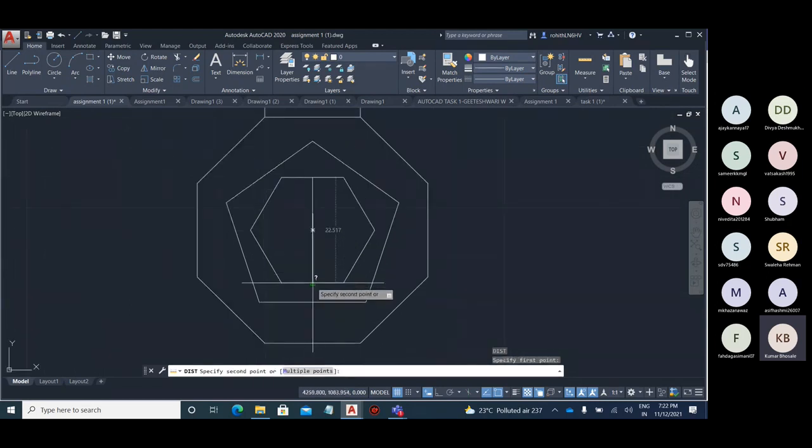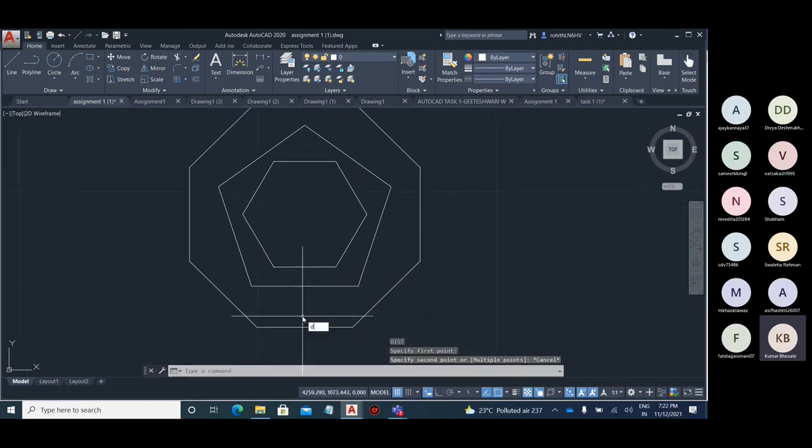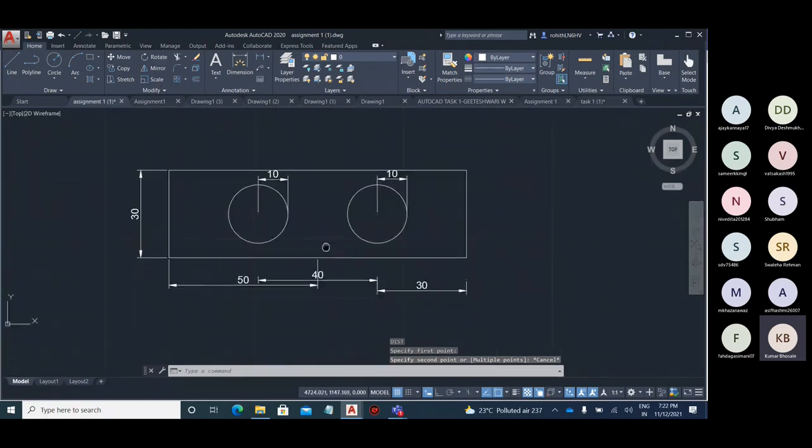Over here this is wrong. This is again created as an interior circle. That is not a circumference, so make sure of this. This is an inscribed circle. Polygon is created by having an inscribed circle. It should be circumscribed. So you can see the distance is 22.517 and the distance given is 26. So this is not created perfectly. This distance from here to here should be 6. It is given as 8.771. So this is also wrong. Please check that.